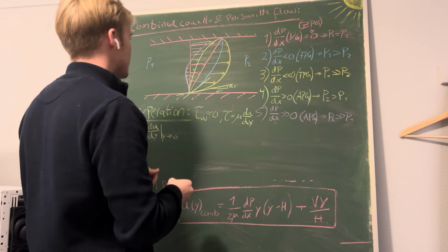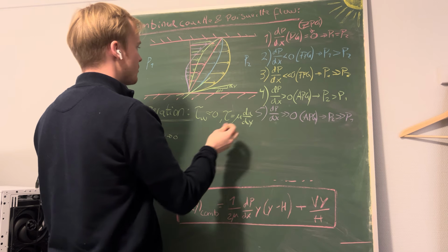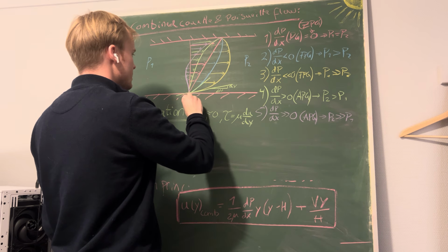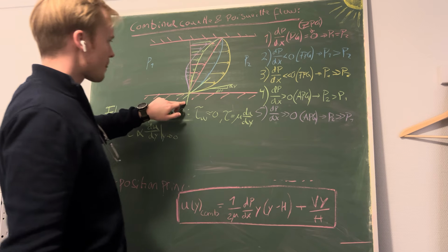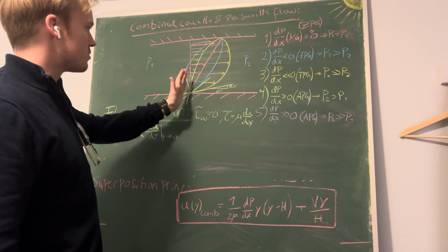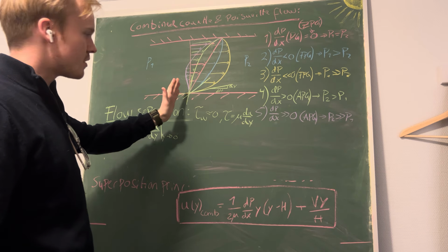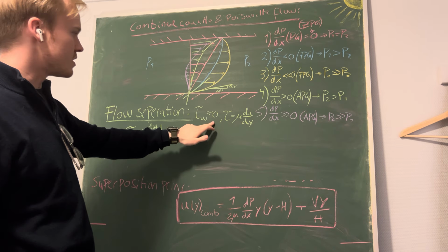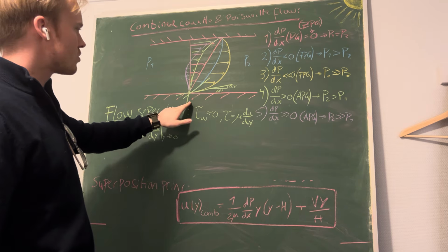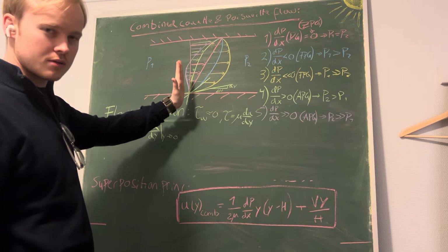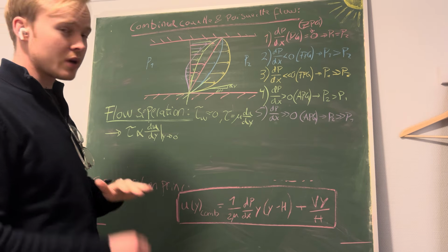And let's look at when we have an adverse pressure gradient, cases 4 and 5. We see that this gradient here is looking almost 90 degrees. So that is on the very verge of having no shear stress. When this comes close to tilting perpendicular or vertical like this, then we have no shear stress.